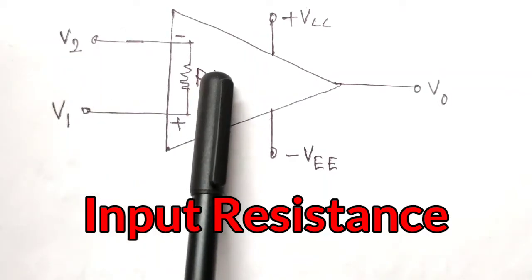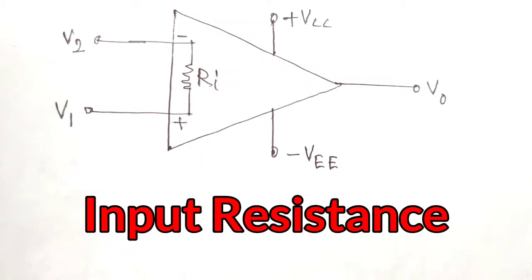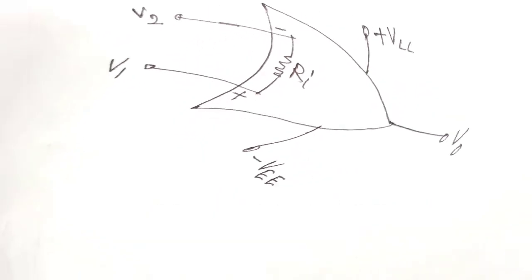Input resistance is the resistance that actually opposes the input current flowing into the op-amp. As you know, for an ideal op-amp the input resistance is infinity, but for IC741C, the input resistance is about 2 mega ohm.